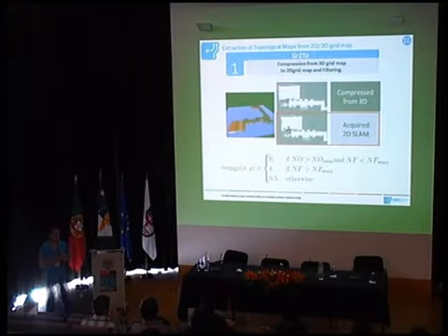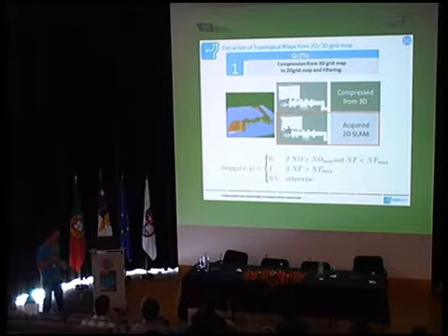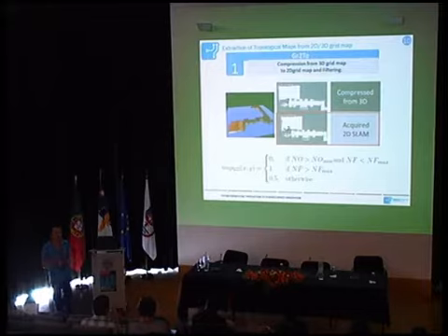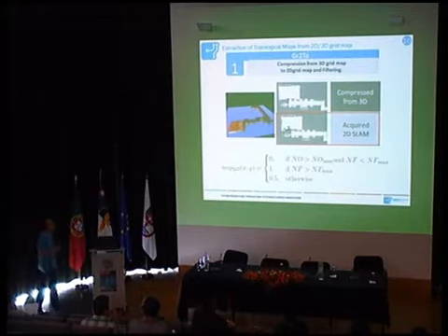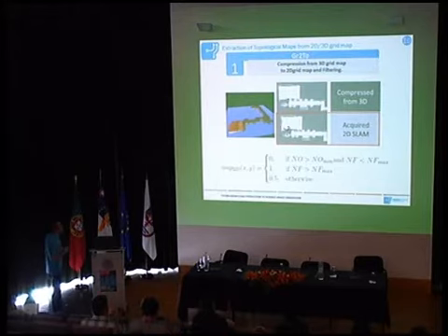How do we compress a 3D map into 2D? This is a simple process. We pick layers, imagine defined by the level from 0 meters to 2 meters, and we compress that into a 2D map, following a rule. A cell is occupied if the number of occupied cells is above a number predefined as a parameter, and the number of free cells is lower than the max cells.